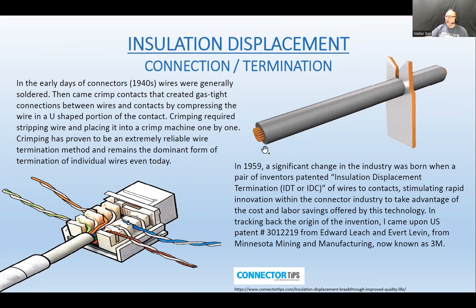Do not use stranded conductors for insulation displacement connection, except for one thing, and it would be in the patch cord. When you crimp the Ethernet jack on the cable, the inline modular jack, some of the connectors are designed for it because it's also an insulation displacement connection.